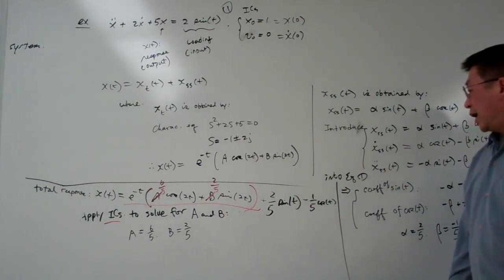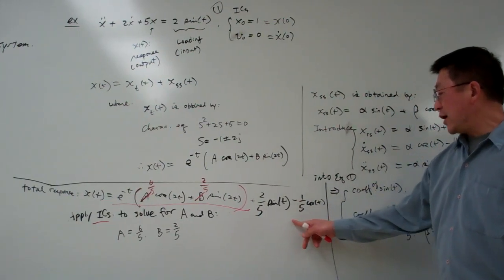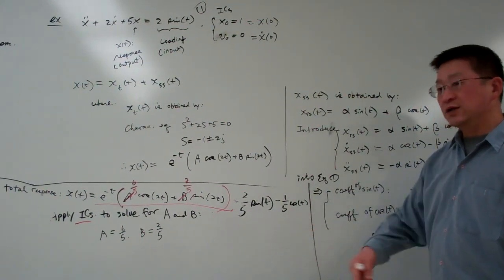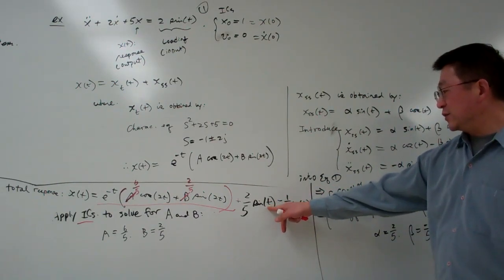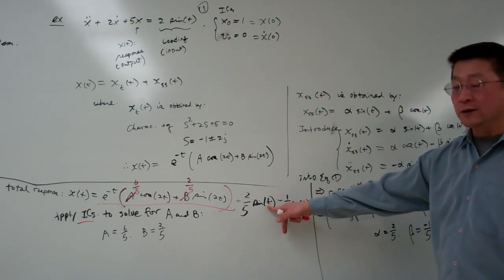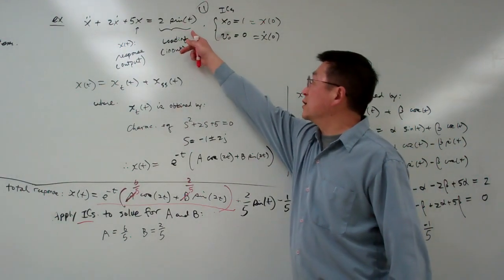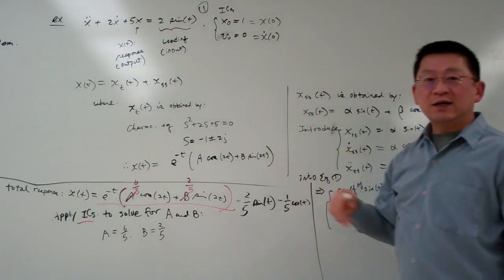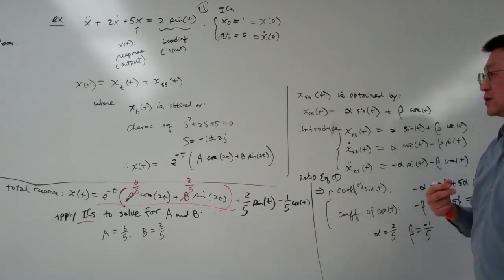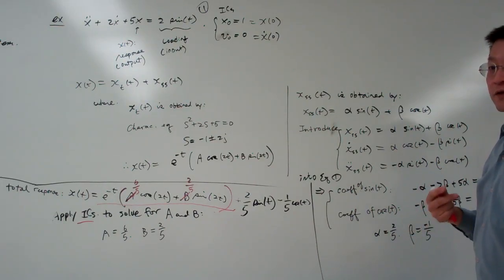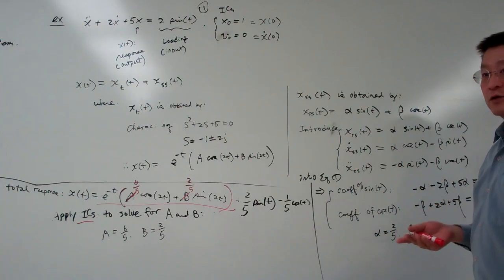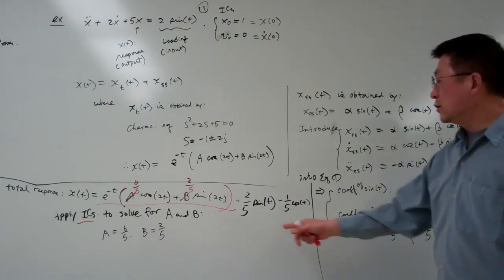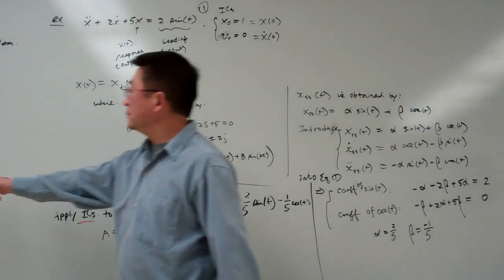When time goes to infinity, the remaining two terms keep oscillating at the frequency of 1, following the given loading. So the steady state response is simply determined by the external loading. Eventually the system follows the same pattern as the external loading.